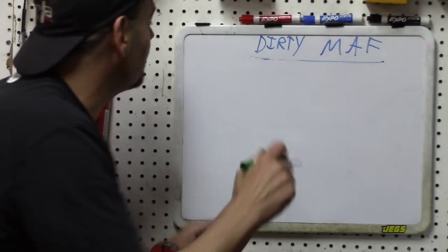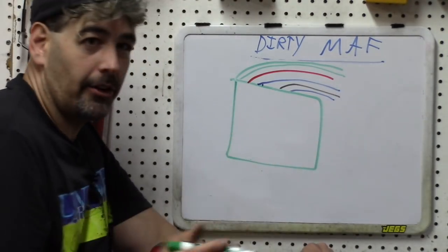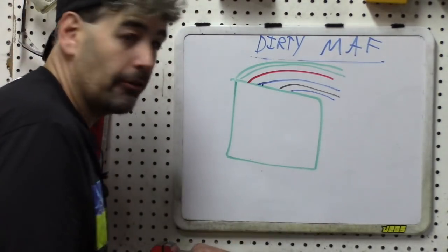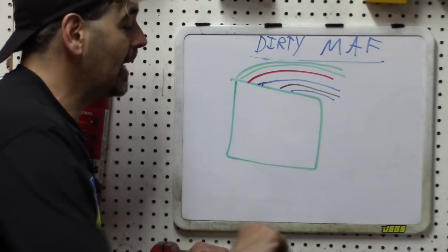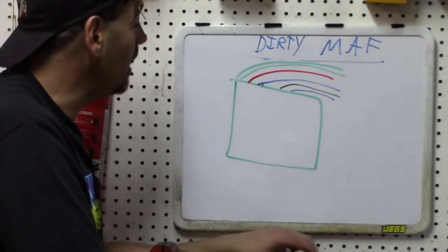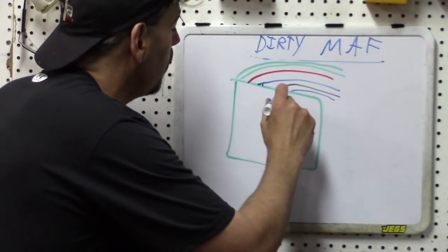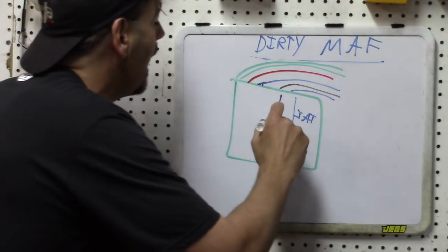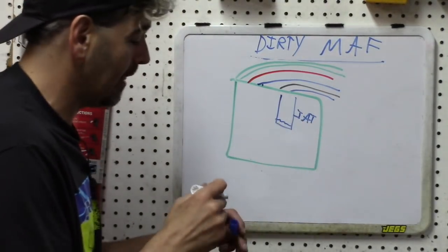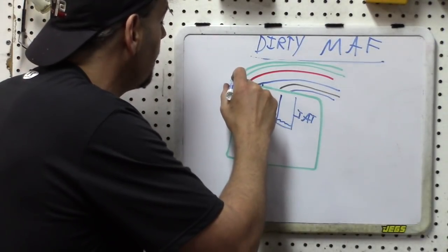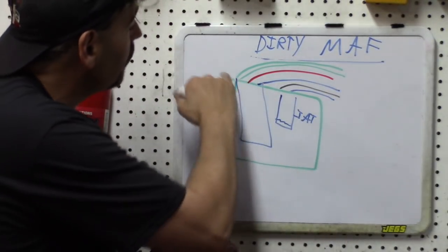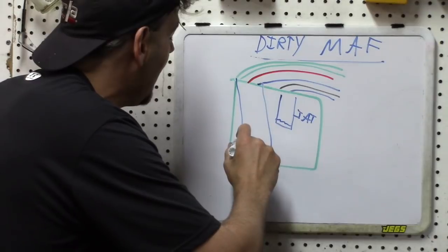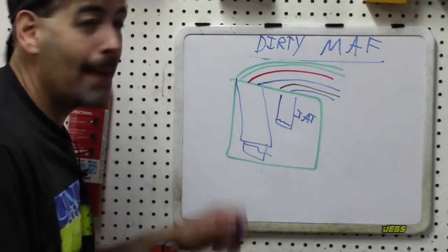Now, when I did that, I did not pay attention that this vehicle actually had, I believe it was either a 5 or a 6 wire mass airflow sensor. So as stated at the beginning of the video, this means that there were actually 2 components here. One of them was, of course, going to be the IAT, which actually had a little kind of resistor looking thing on it. And then the other components here, I believe it had 2 grounds, one for the power wire, one for the 5-volt reference. It had a hot wire MAF here.